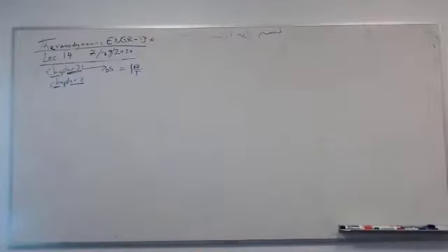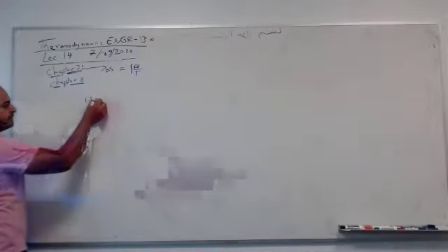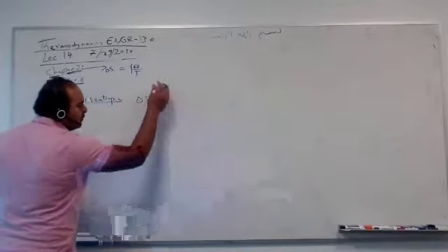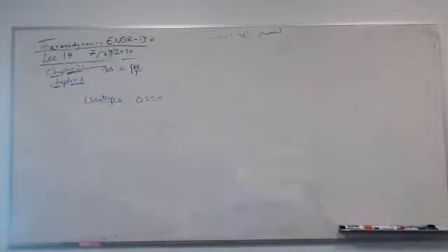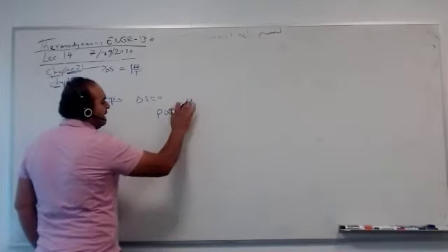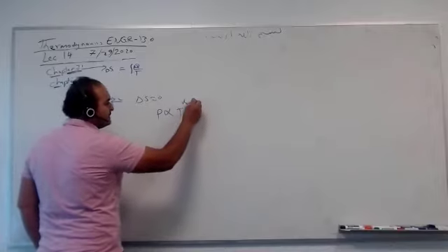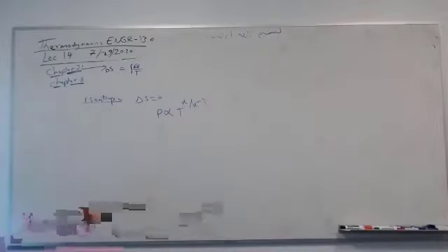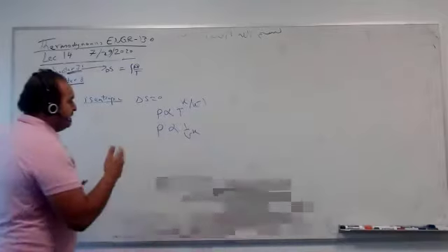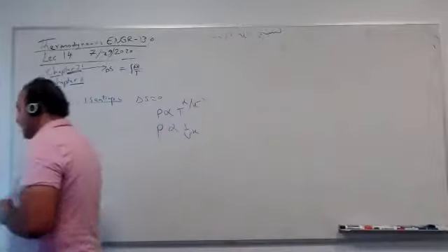So we jump to isentropic. There is something called isentropic, when delta S equals 0. For all these cases, for solid and liquid, temperatures will be the same. For gases, we said P is proportional to T to the K over K minus 1, like today's quiz. The same for P proportional to V to the K, where K is the specific heat ratio. The relations between P and T, P and V, and T and V are given in the exam or in the book.